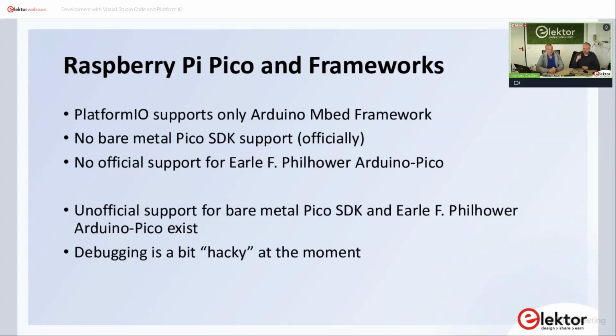With the Raspberry Pi Pico, we come into another weird situation. For the Arduino framework support, there are two software frameworks around. One is the official Arduino framework from the Arduino guys for their RP2040 Nano Connect, which is based on the Mbed framework, the ARM RTOS.